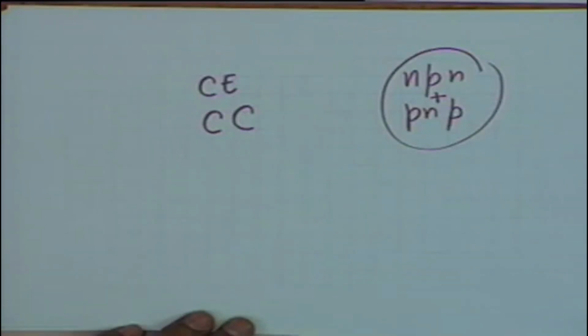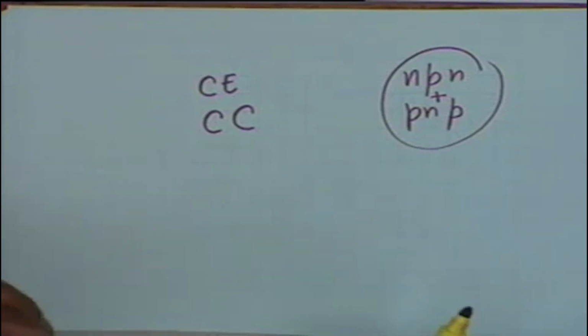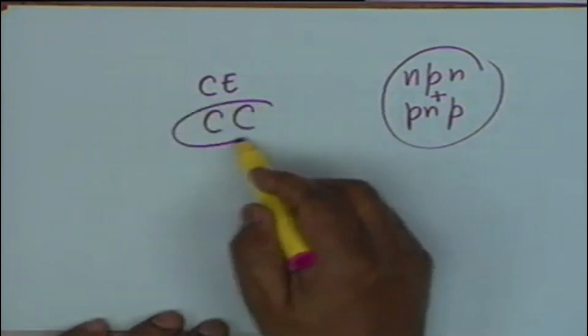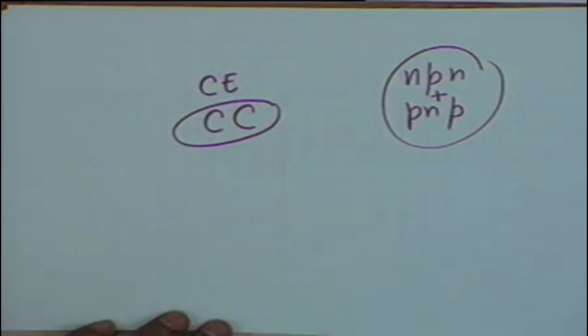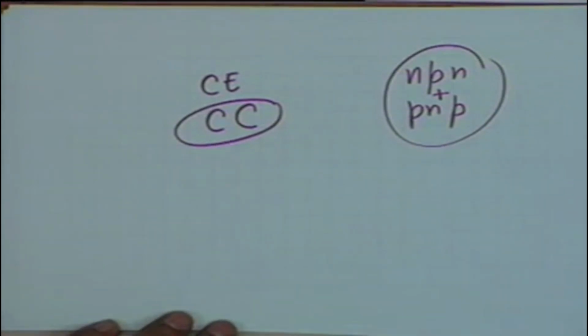This circuit uses what is known as, well, you have known common emitter amplifier. This circuit uses common collector stages, that is, each of these stages, NPN and PNP stage, which are connected in a push pull configuration, they are, instead of CE, they are CC. That means the collector is common between input and output.